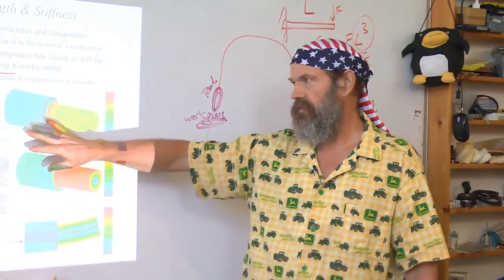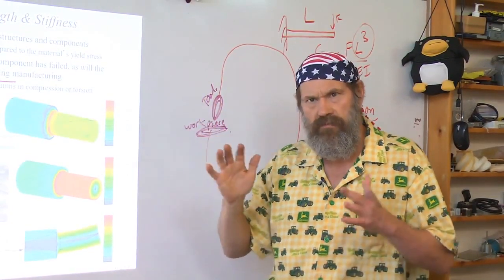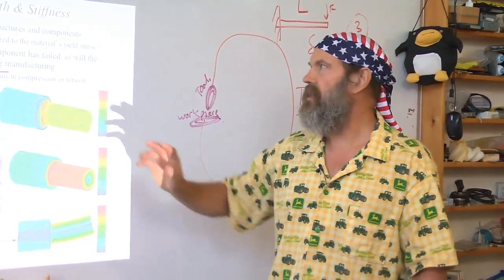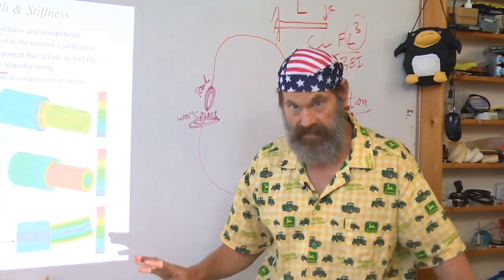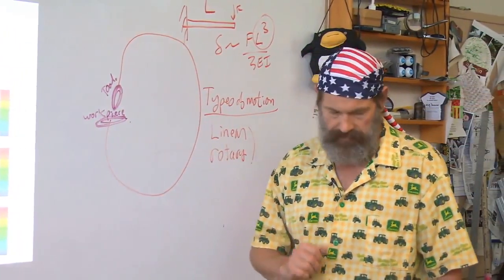The modulus of elasticity of all aluminums is the same. Small variations for rolling direction, heat treatment, but never assume that I can make a material stiffer by heat treating, for example. No, it doesn't work. You have to physically change the type of material.